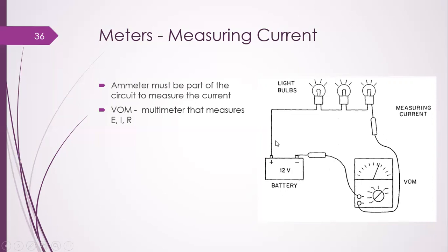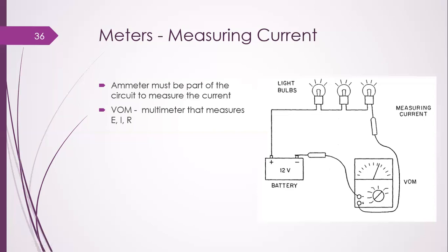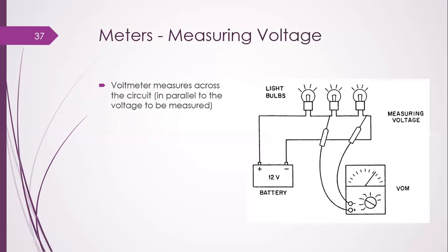We also know that in a series circuit the current is the same throughout the circuit, but if we connect in parallel, then the symmetry would change. So we are not complicating the situation. We assume the same scenario to measure the voltage and the current. The difference is that if we need to measure the voltage, we connect the meter with the particular load in parallel. Then the voltage would be found on the meter screen.